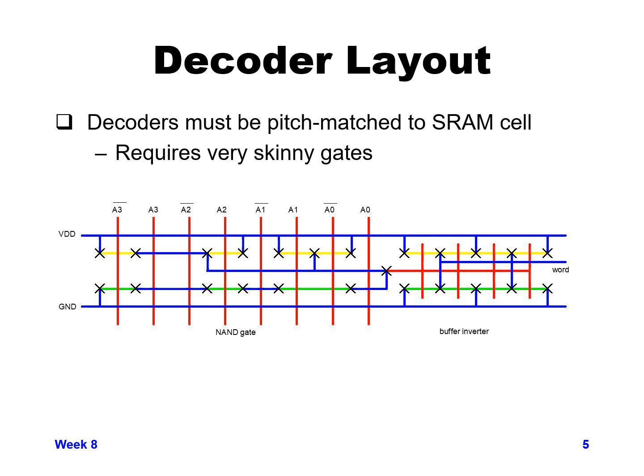Keep in mind, you don't use regular standard cells when you're driving word lines and bit lines for arrays. You have to make sure to pitch match to your rows for your word line cells and pitch match to your columns for your bit line drivers and read devices.